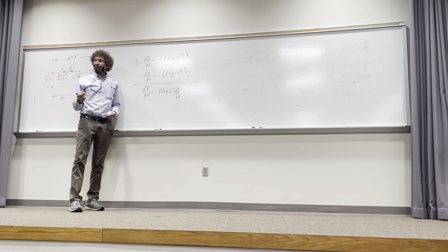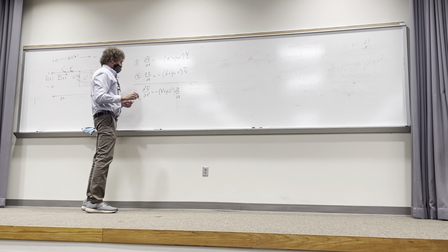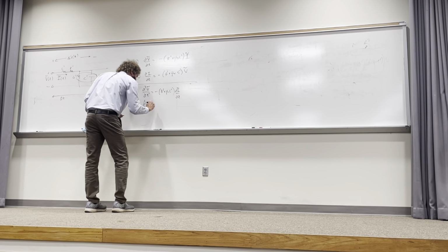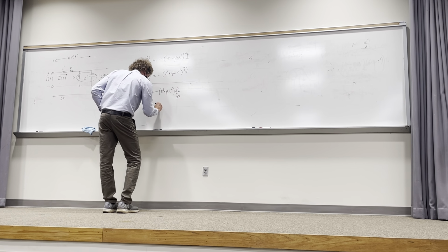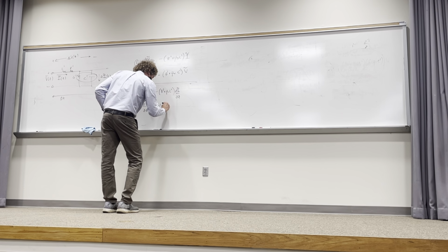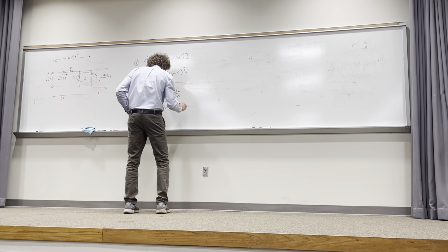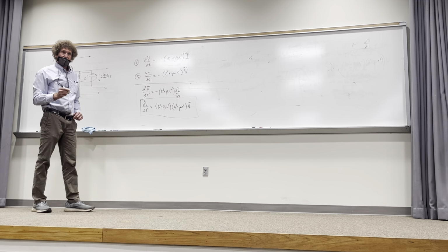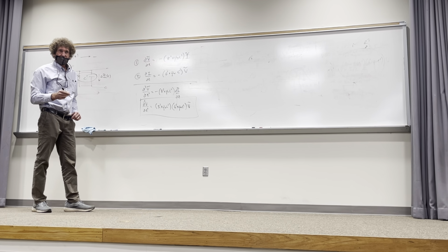And the way we got rid of that dI/dZ is we replaced it with this second equation. So then what we end up with is the second derivative of V with respect to Z squared is equal to, these minuses will cancel each other and they become, R prime plus J omega L prime times G prime plus J omega C prime times V. And that's where I left off last time. Y'all remember this, class? Can y'all follow me? Just look at your notes and you'll see this is exactly where we left off.